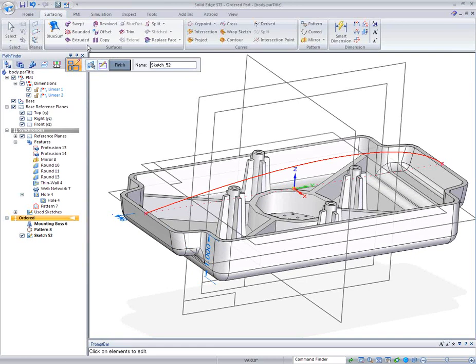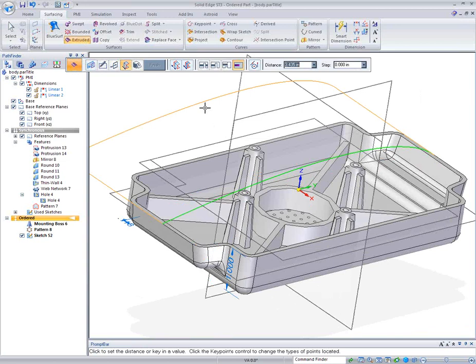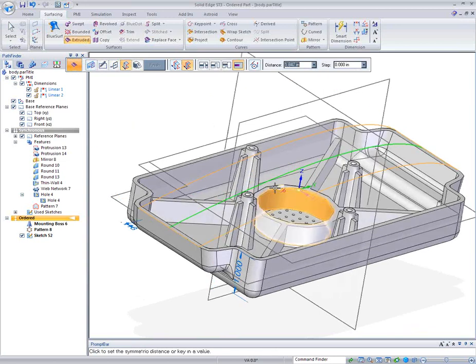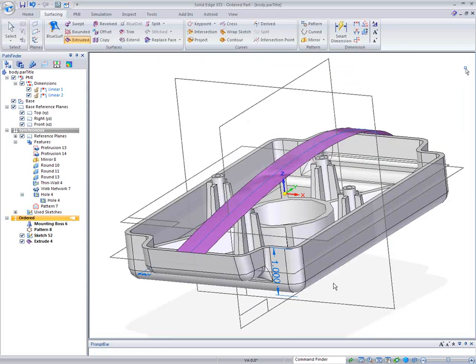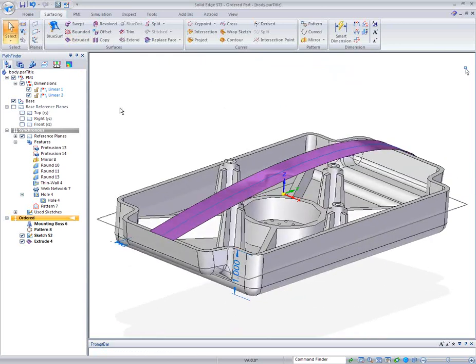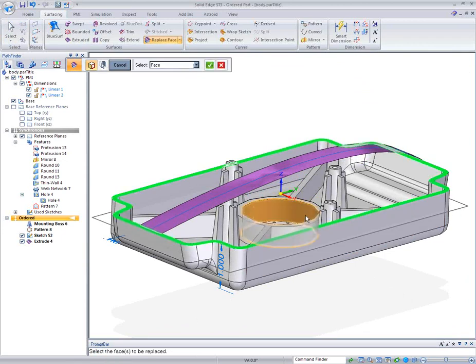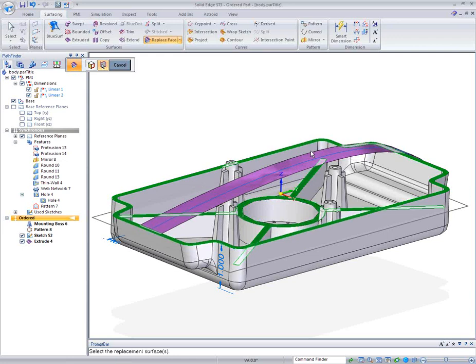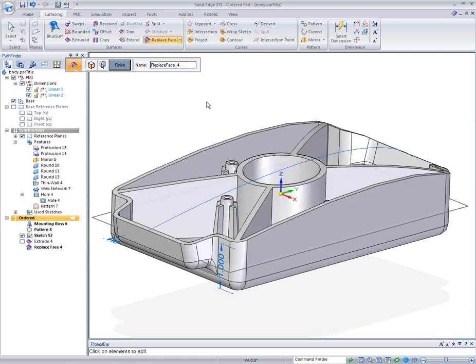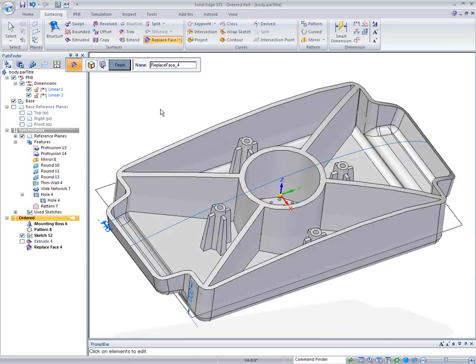So now we'll go ahead and make an extrude surface, and I'm going to come out just a touch, and I just want to show you a very, very neat feature that we have here. I'm just going to come out with almost a piece of tape setting out here, just that thickness. And as I do, I'll go choose to replace a face, and I'll replace this and then this right up here. I'll replace both of that with this, and then the part will just simply adjust to be exactly what I want. So very, very strong, very, very powerful set of tools.